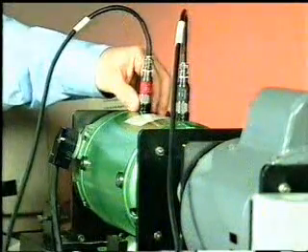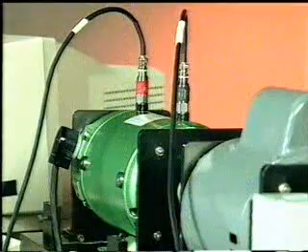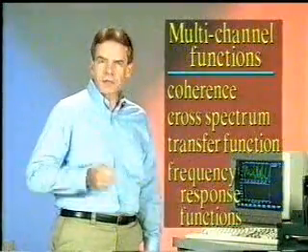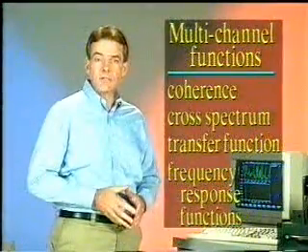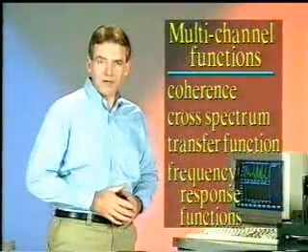And for a vertical to vertical comparison, it must be moved to one of the vertical points, and so on. The second difference is the multi-channel has the ability to look at any frequency of interest. Another advantage is the data is stored as spectral and waveform data, allowing you at your convenience to perform any analysis, including cross-channel phase, which is only one of many multi-channel functions.